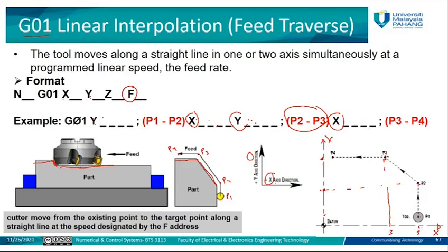You are already at this point, so it just continues at the same position. Go left by, for example, if this is 1, it will go left by -2, to +1. If incremental, it will be -2. If absolute, it will be 1. So this is how to use the G01 code in the program.